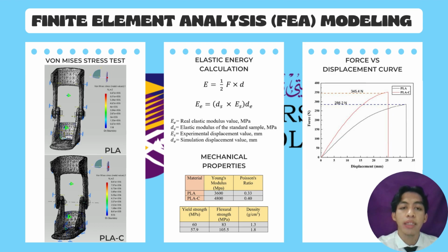Materials are often categorized using force displacement curves. These curves are a result of experimental analysis. Using the first equation, elastic energy may be computed based on the connection between force and displacement. This method of calculating elastic energy has been used to examine how the AFOs deform under stress. The simulation deformation distribution plot and von Mises stress distribution were utilized to compare the experimental findings.